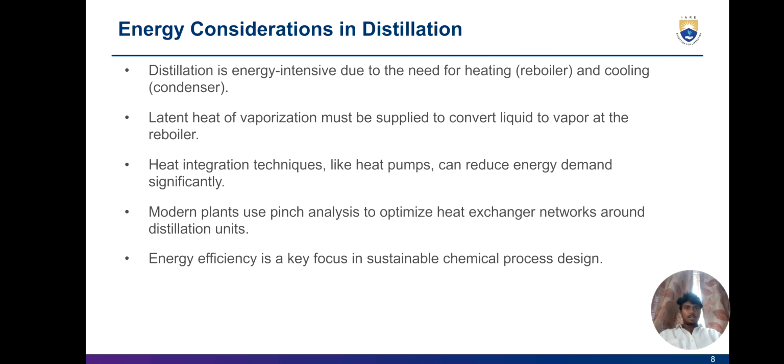Energy considerations in distillation. Distillation is energy intensive due to the need for heating and cooling. Latent heat of vaporization must be supplied to convert liquid to vapor in the reboiler. Heat integration techniques like heat pumps can reduce energy demand significantly. Modern plants use pinch analysis to optimize heat exchanger networks around distillation units. Energy efficiency is a key focus in sustainable chemical process design.